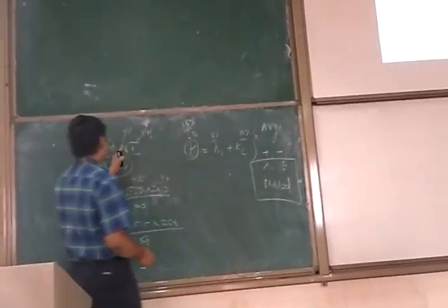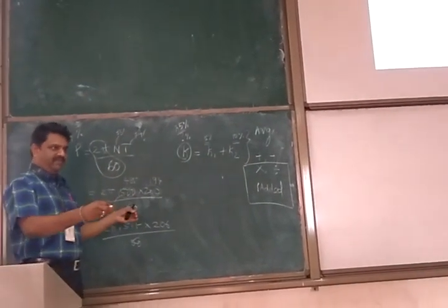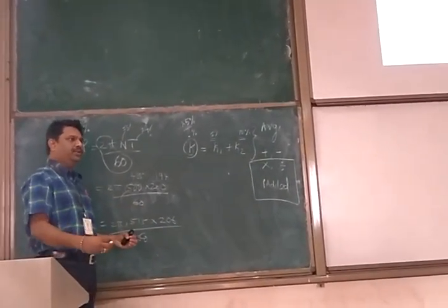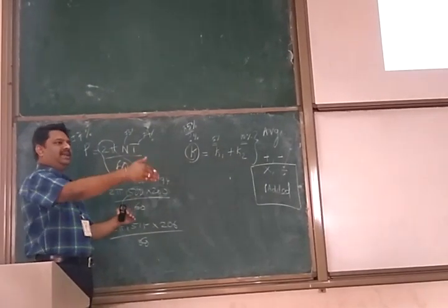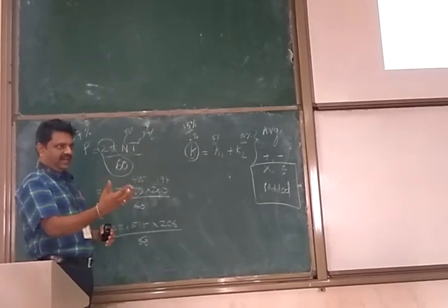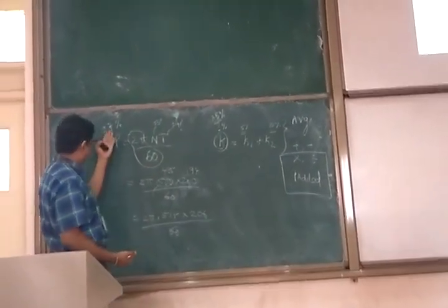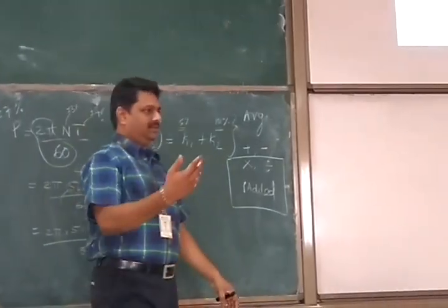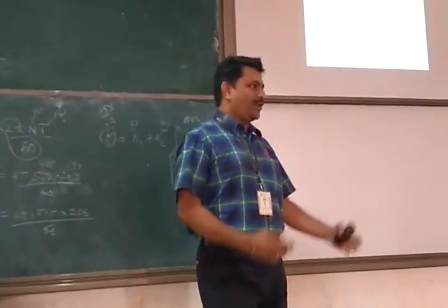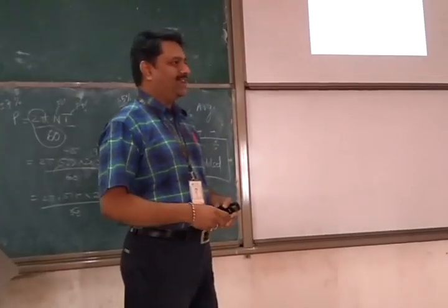You will see that even with some parameter divided by some parameter, you can find out the extreme minimum value, the extreme maximum value, and the nominal value. Nominal minus any one of these extreme values will give you the error. The error divided by the nominal value into 100 will give you the percentage of error on the final parameter. Take it as a tutorial for take-home work and try it out. If it is not working, come back. We will sit and sort it out.